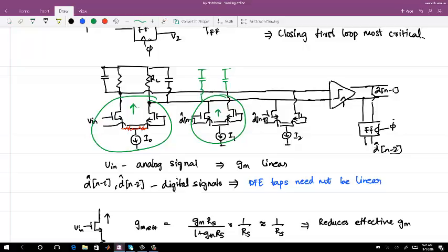If you say it is going to decrease the headroom, I can say I will use an optimum voltage such that the headroom remains fine. So I will decide my switch size such that my headroom is there and I do not cause any problem due to the channel length modulation also, and the size is minimum because the parasitic capacitance is important here.